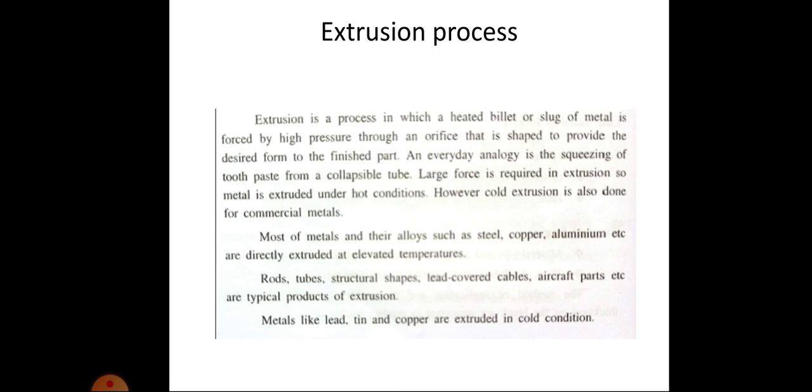Most metals and their alloys such as steel, copper, aluminum, etc. are directly extruded at elevated temperatures. Rods, tubes, structural shapes, lead covered cables, aircraft parts, etc. are typical products of extrusion. Metals like lead, tin and copper are extruded in cold condition.